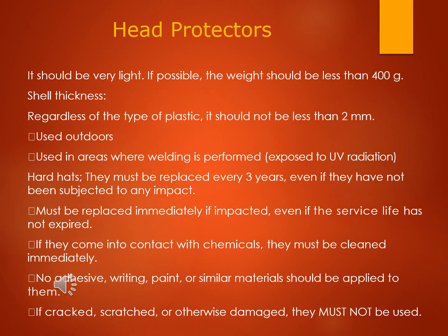Head protectors should be very light. If possible, the weight should be less than 400 grams. Regardless of the type of plastic, the shell thickness should not be less than 2 millimeters. Hard hats must be replaced every 3 years, even if they have not been subjected to any impact. They must be replaced immediately if impacted, even if the service life has not expired.